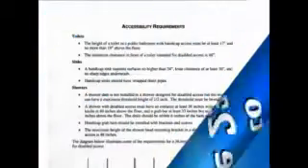We're going to be talking about accessibility requirements. Toilets. I'm pretty much going to have you read through this page on your own. However, for the moment, we're going to circle or at least highlight a couple of important items. And the first one is on the very first line there. Height of a toilet in a public bathroom with handicap access must be at least 17 inches. Maximum 19 inches above the floor. So mark 17 inches and 19 inches.